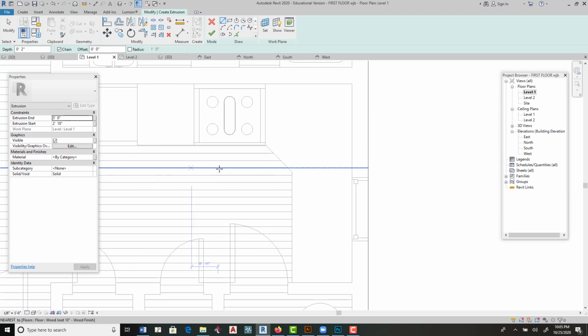Now remember, when we put the countertop in, the countertop started at 2 foot 10 above the cabinet, and it ended at 3 foot 0 because it's 2 inches. 2 foot 10 plus the 2-inch countertop that we place is 3 feet. Now the backsplash starts at the 3 foot 0 countertop. So starting at 3 foot 0.